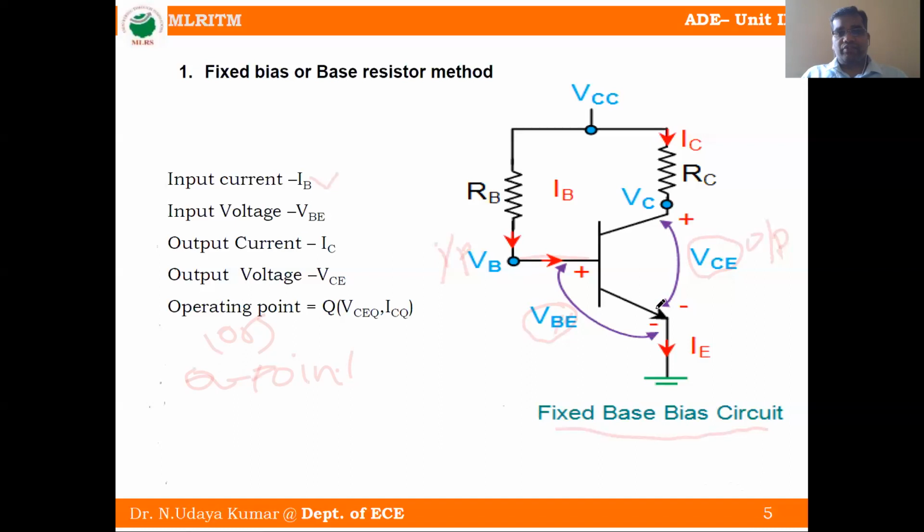So first analyze the circuit, which configuration. See, you can clearly analyze: one resistor in the common emitter terminal, one resistor in the base terminal. This resistance RB is nothing but the base resistance. The base resistance is connected to VCC, the supply voltage at the collector terminal, and directly connected to the base terminal. This RB has a high value. Whenever there is zero signal, that means we are not applying any signal to this circuit, this battery provides the voltage to flow the base current to the transistor and maintain the IC value.